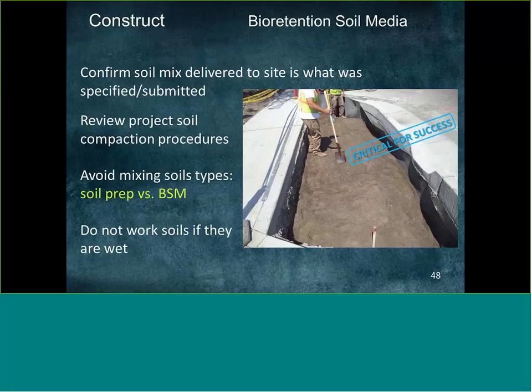You're going to till in and add some compost to the landscape next door, but the bioretention section needs to just be bioretention. So you don't want the contractor going in and amending the soil on the adjacent landscape and dumping that into the bioretention soil, because, depending on the soil type, it could potentially clog it. They also need to know they can't work in wet soils. That can over-compact the system.